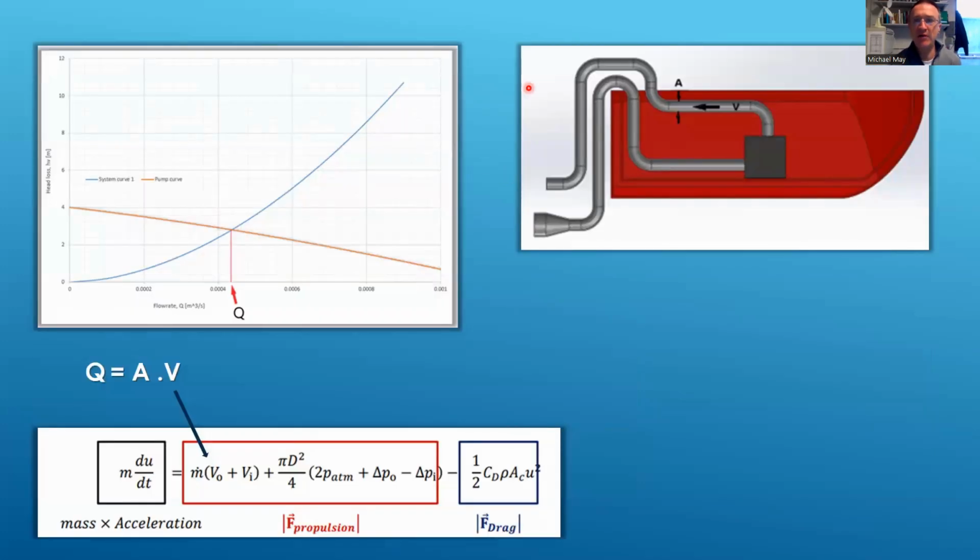So let's say you have your outlet pipe designed like this, but it doesn't have a nozzle at the end. What you do is you work out all your major and minor losses in that outlet pipe over a range of flow rates, and you produce your pipe characteristic curve. You then superimpose your pump characteristic curve, and where they intersect is the operating point. And drop that down onto the x-axis, and you'll get your flow rate, your volumetric flow rate that system is providing.